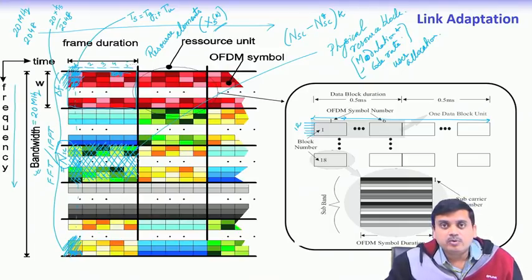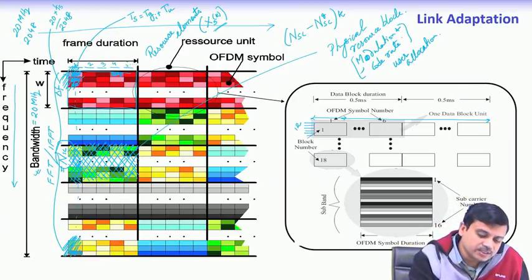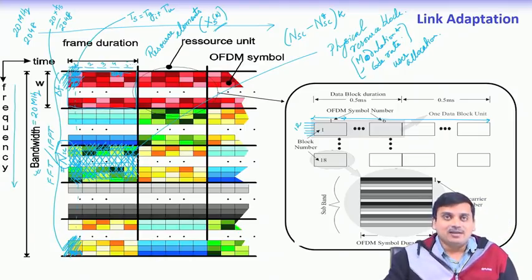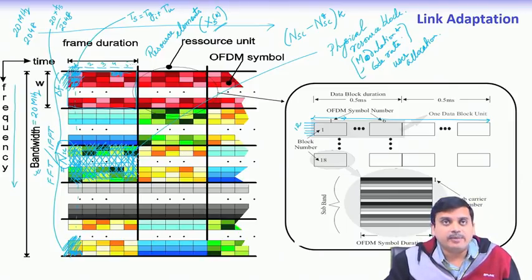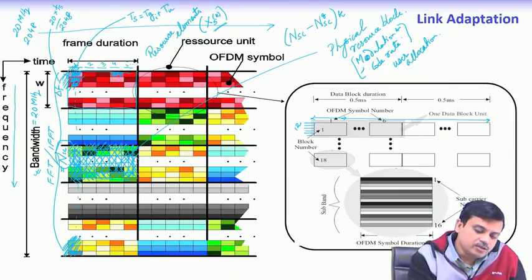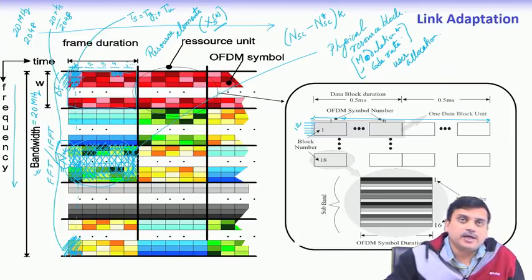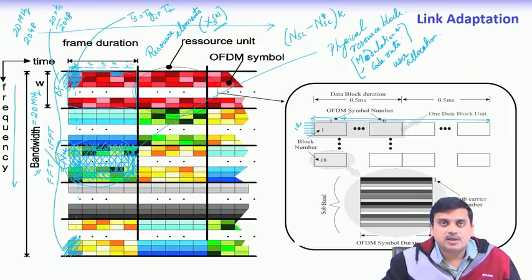Whenever we do any resource allocation or any link adaptation, we would be doing it over this entire block of symbols simultaneously. This will only reduce the amount of overhead. Further, the channel, which fluctuates in both time and frequency, remains roughly constant over one such period, and hence it does not make much difference to allocate them in a different manner.